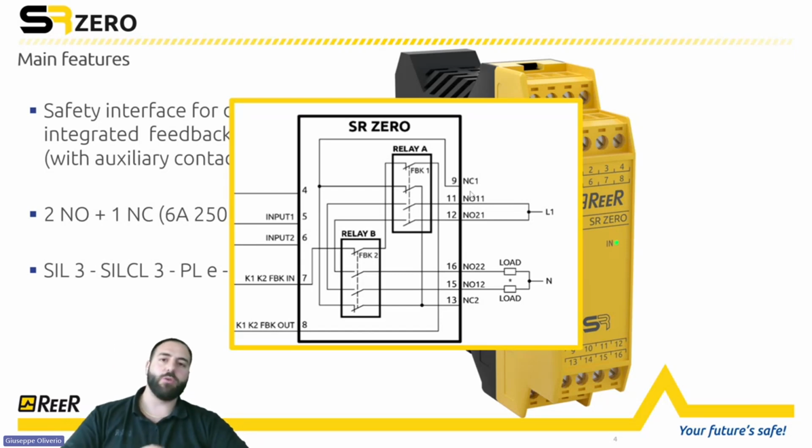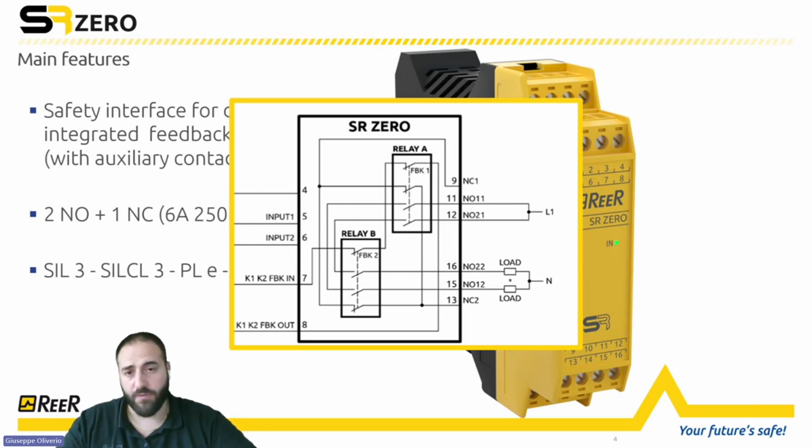The combination between the safety device in category 4 plus this SR0 is the complete set for a category 4 application. So by using, for example, our light curtain, a type 4 light curtain plus the SR0, you can reach category 4. So you can mount it in an application that requires performance level E.